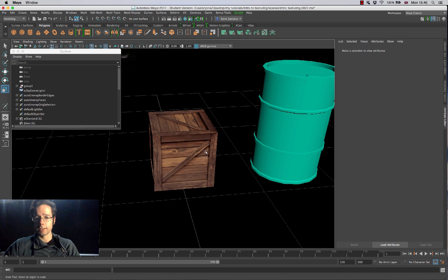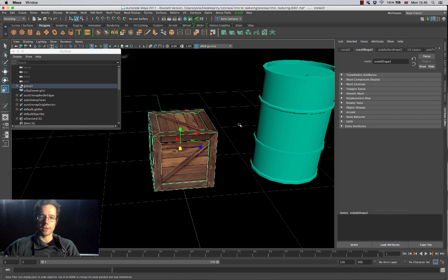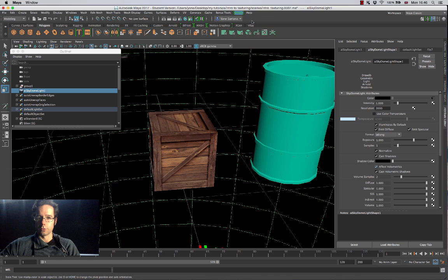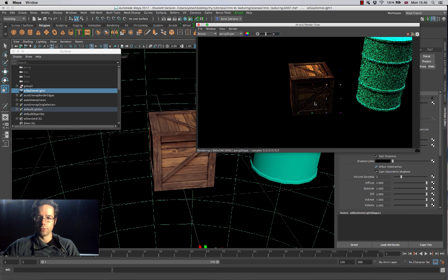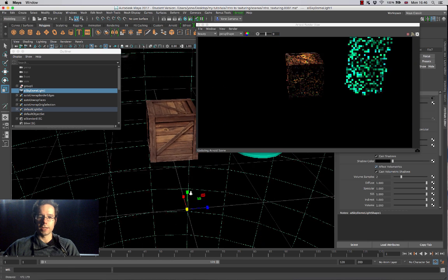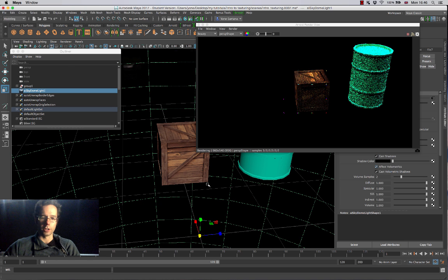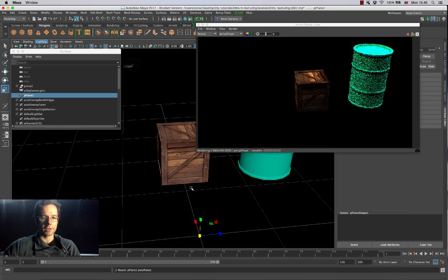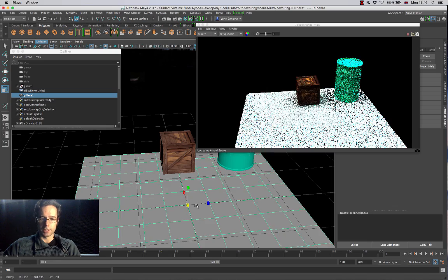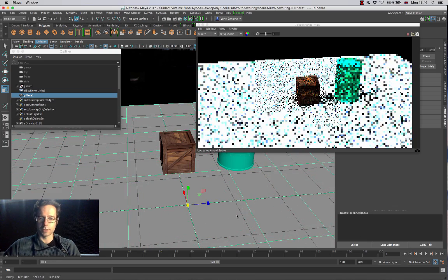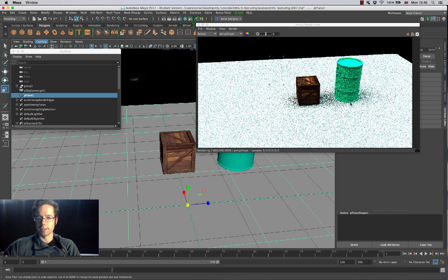And what you can do again is grab yourselves your objects of any sorts, and if I turn on the Arnold render view again, you're going to see that this material over here is going to look reasonably nice like that. Another thing that's really interesting about Arnold as well is that if you just create a simple polygon plane over here and we scale it up as best as we can, so if I just click here and create an image plane, you're going to see that the materials that come in by default, like this one over here, are going to cause some indirect illumination onto the actual object as well.